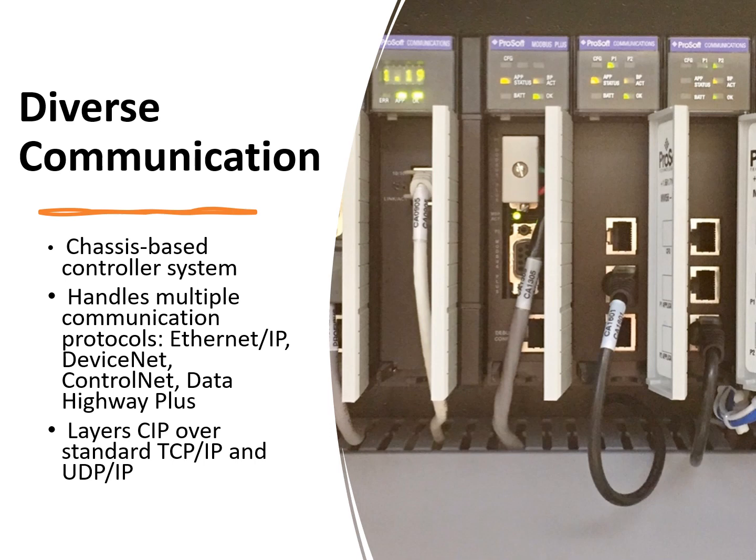This system, shown in the figure, has the capability of handling multiple communication protocols such as EtherNet/IP, HART, DeviceNet, ControlNet, Data Highway Plus, Foundation Fieldbus, and Ethernet. Further, it supports programming languages such as ladder logic, structured text, function blocks, and sequential functions.